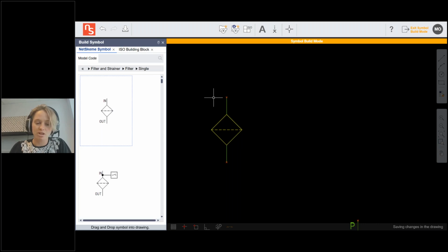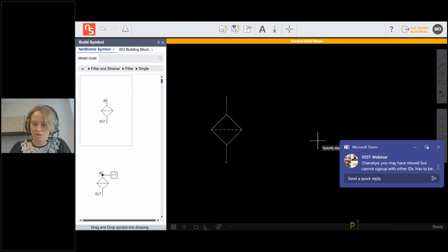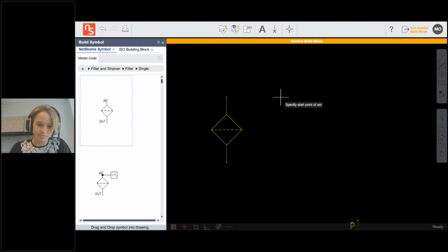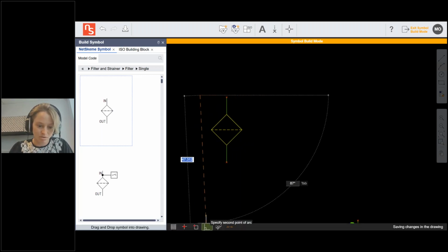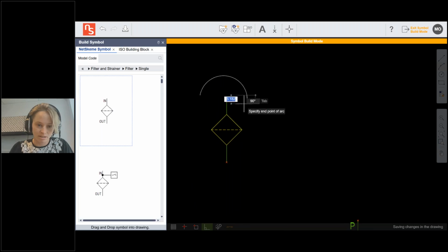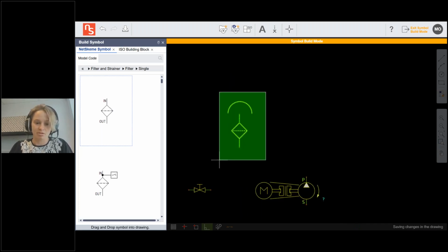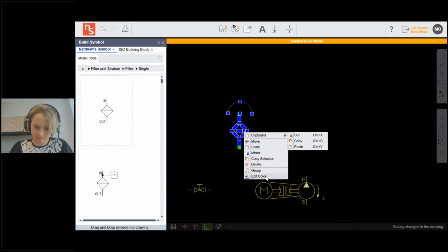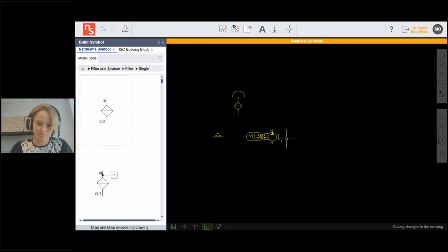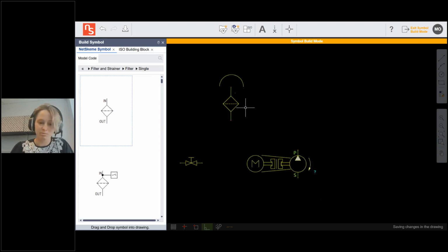And I also had a shape on top of this that I'm just going to create. So I'm going to turn on ortho mode to make this a straight line. There I go. So you'll notice this is a different color. I can use the match properties command to take the source color and match it there. And I'm going to group all of this as one symbol now. Group. There we go. So now, oh, we have one more filter.